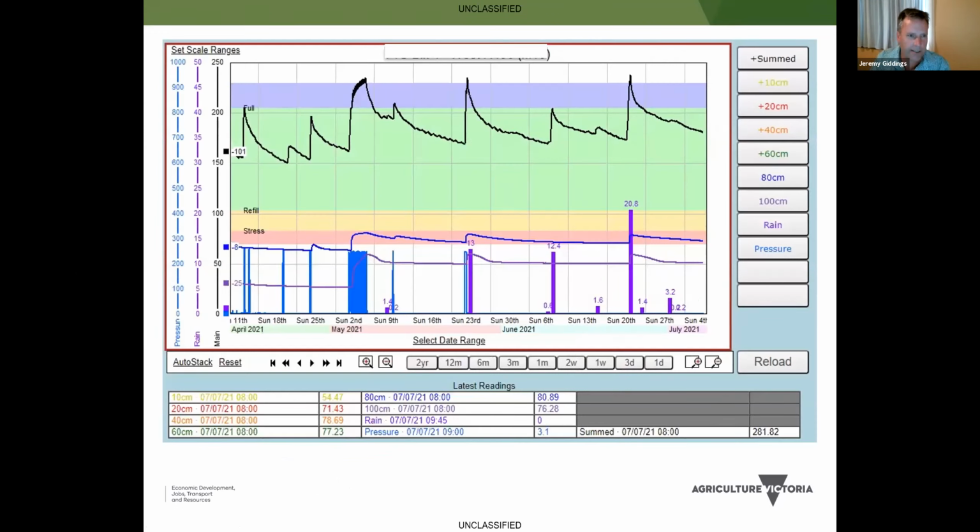The thing we're starting to see more and more is integration, and this is a similar irrigation trace at the top here, but at the bottom we have integrated rainfall events from a weather station. You don't have to enter these manually anymore. And you've also got a little sensor out in the field measuring drip line pressure. So that is a substitute for irrigation events, and you can see each of these blue ones are an irrigation event and a corresponding rise in the irrigation trace. And in the middle of May here, that valve got stuck on, and you can see the end result.